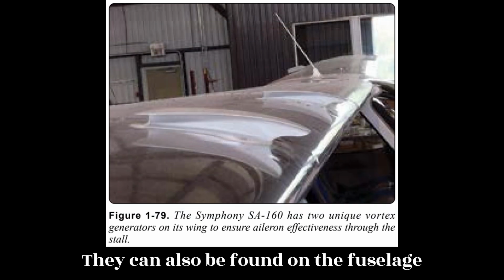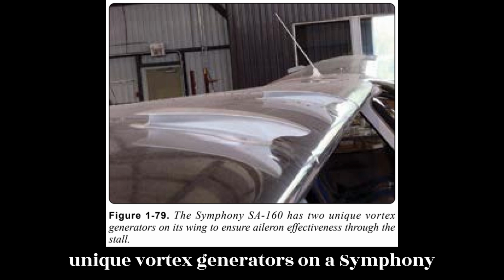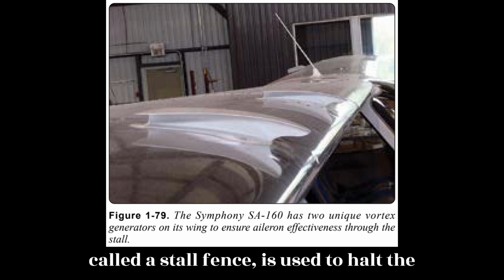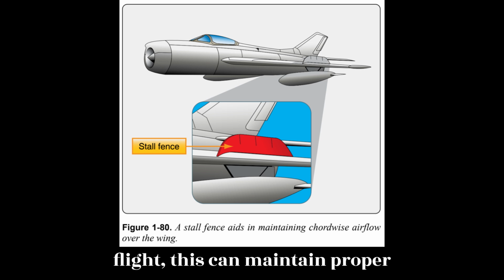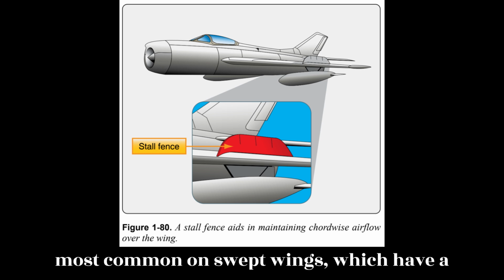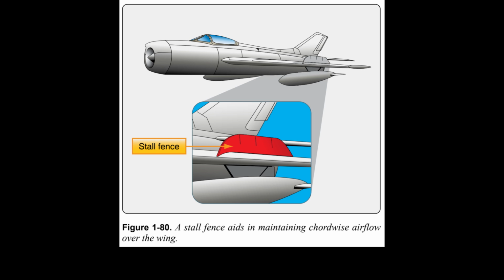They can also be found on the fuselage and empennage. Figure 1.79 shows the unique vortex generators on a Symphony SA-160 wing. A chordwise barrier on the upper surface of the wing, called a stall fence, is used to halt the spanwise flow of air. During low-speed flight, this can maintain proper chordwise airflow, reducing the tendency for the wing to stall. Usually made of aluminum, the fence is a fixed structure most common on swept wings, which have a natural spanwise tending boundary airflow. Figure 1.80.